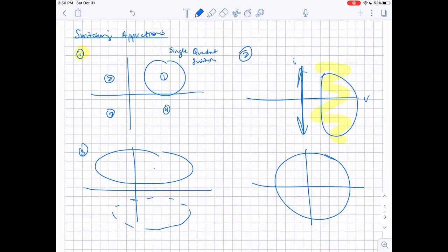And then you have the most complex case, and obviously the most general. It's the hardest to control and realize with semiconductor devices, obviously, because you can be operating however it wants. It could be the case 1, 2, or 3, or it can be operating with all the quadrants. So especially in AC to AC devices, you're going to need 4 quadrants. It can block positive and negative voltage when it's off, and it can conduct either positive or negative current when it's turned on.